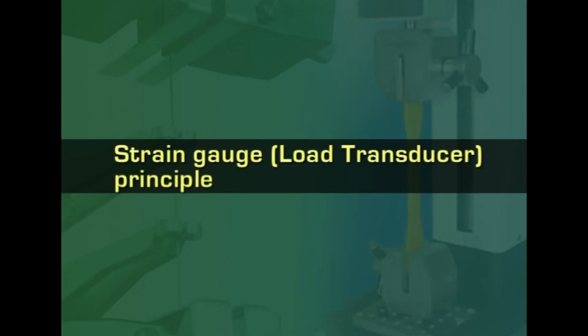Then let us look at the strain gauge principle, and the strain gauge principle is based on measuring the changes in electrical resistance of the upper and lower planes of a flat spring as a result of changes that occur in its shape due to tensioning of a specimen till it breaks.